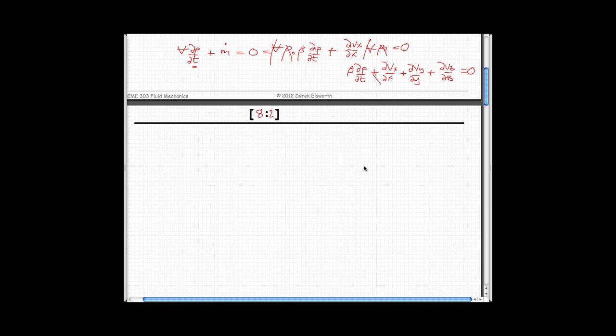Is by realizing that this is mass in minus mass out equals mass accumulation. That's all. It's written in terms of pressures here, so we'd like to be able to define this whole thing in terms of pressures. So how do we do that? And what we use is a law, and it's a law you might have heard of, Darcy's law.